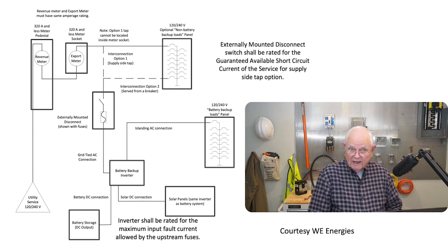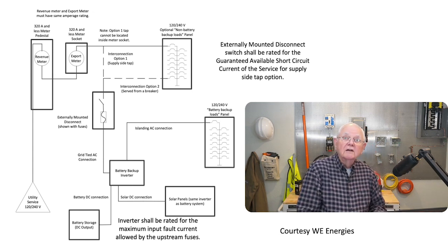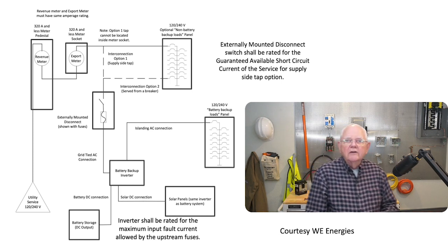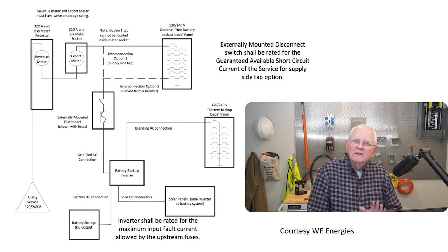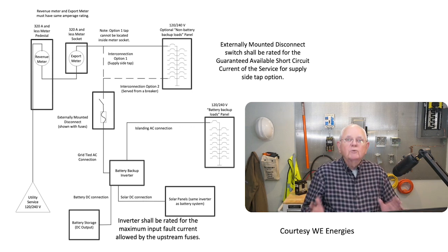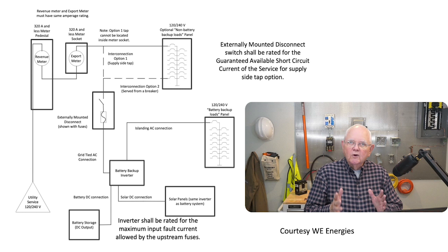Sure, I should have some type of placards that are in accordance with what's in Article 110 about marking requirements and all of that, and have that information on those labels. So I always think of it in an emergency situation when I run up there. I want to know what the voltage is. I'm going to shut that disconnect off.